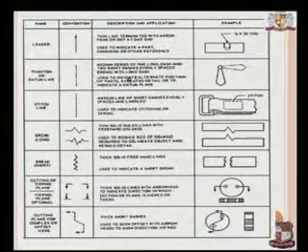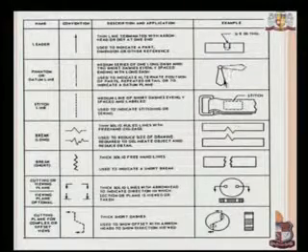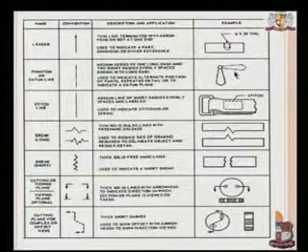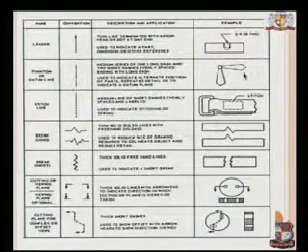Phantom lines, as we discussed, show the initial position and the final position. The initial position is drawn with a continuous thick line or the visible line, and this is the phantom position which will be drawn by the phantom lines or say the datum lines.